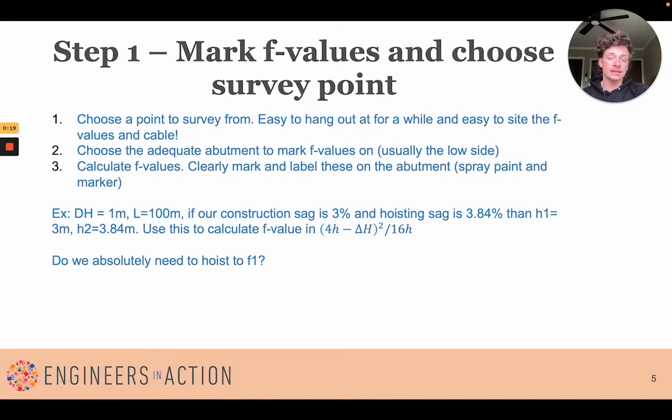And now one last thing is, do we absolutely need to hoist to F1? The answer is no. This is just a minimum value. We definitely don't want to hoist our cables above those F1 values, but we don't absolutely have to hoist to that value. And I'll talk about that in a little bit more later.